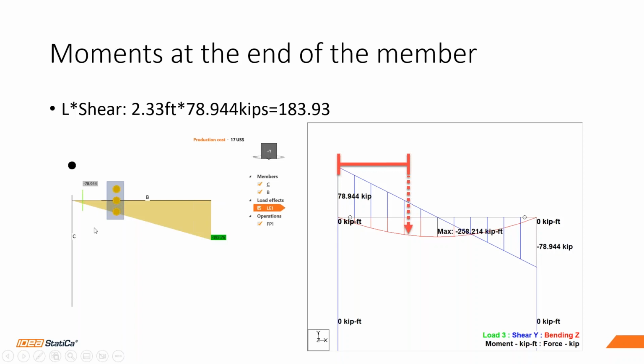Well, with that explanation of where the moment comes from, another important thing is that in this case, this beam to column connection is from the center point of this column and the center point of this beam. So we normally don't model the offsets in your global analysis, right?